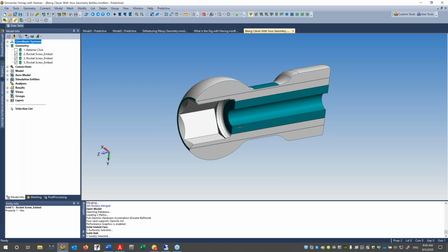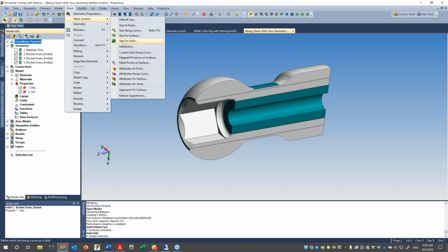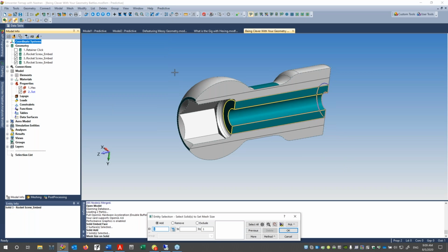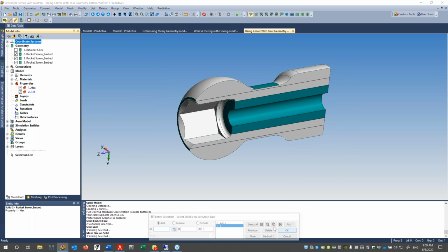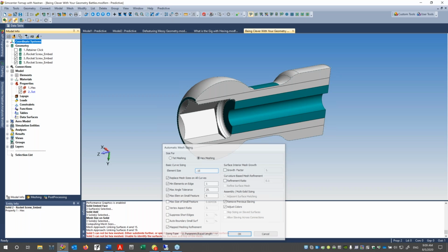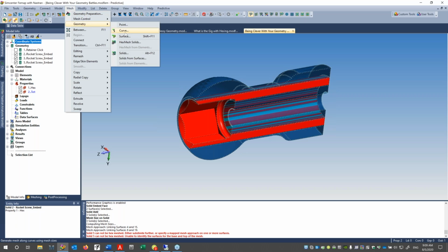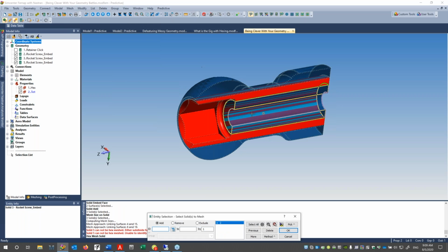So I have 3 solids set up for this, and I've already preloaded the hex and tet into it like that. And this is the gig, is that you go in and you start declaring that you want to make it a hex. And it doesn't look very pretty with that mesh sizing. There we go. I'll make a prettier mesh. And it'll come back and say, oh, look at this. The blue is it can hex. The red, it's unhappy, it won't make it.